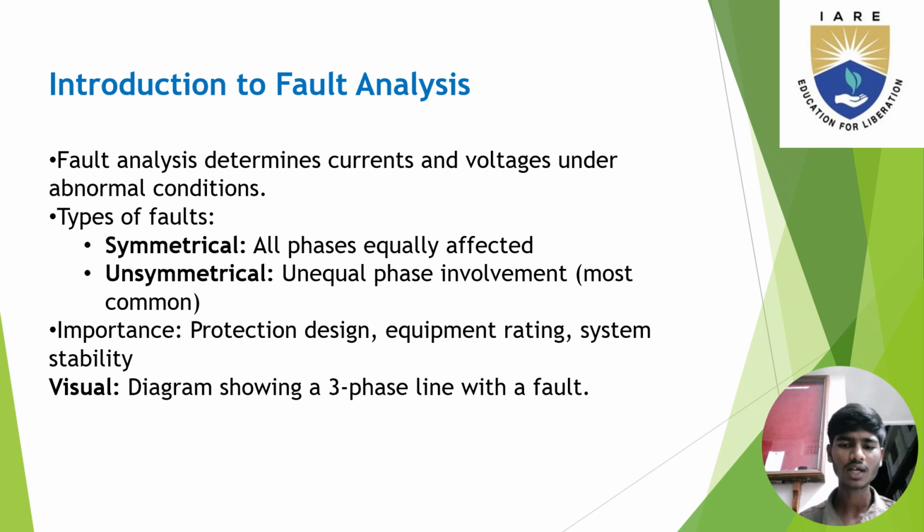Introduction to fault analysis. Fault analysis determines currents and voltages under abnormal conditions. Types of faults: symmetrical, where all phases are equally affected, and unsymmetrical, with unequal phase involvement, which is most common. Importance: protection design, equipment rating, system stability.